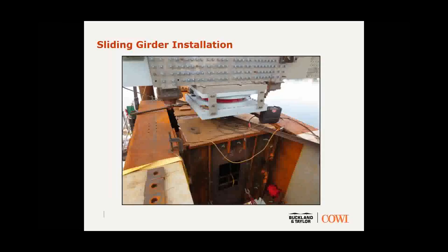So in this picture, there's a lot of stuff in the way yet. Mainly the girder's been prepared where the bearing's going to land. It's been prepared by polishing it and greasing it, so it's covered with plastic and plywood to keep people from slipping. Once all that's cleaned out, then the girder would be lowered into position on top of the sliding girder.